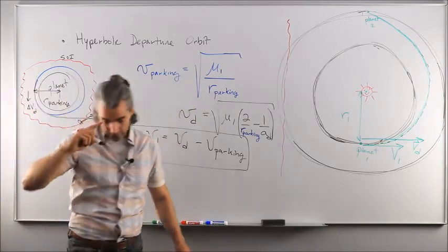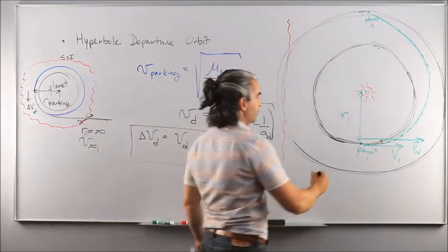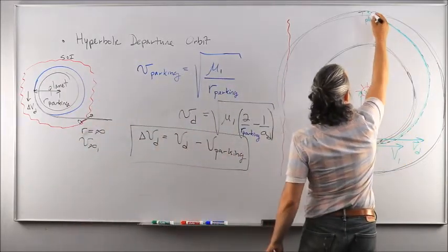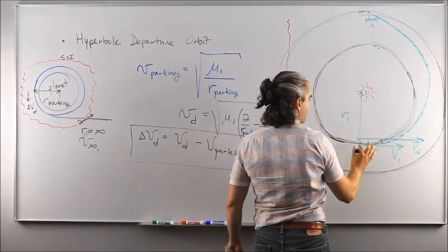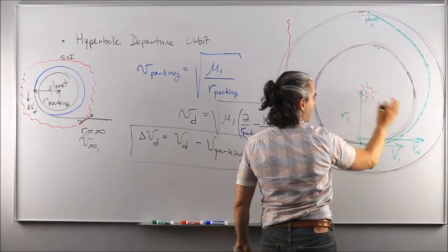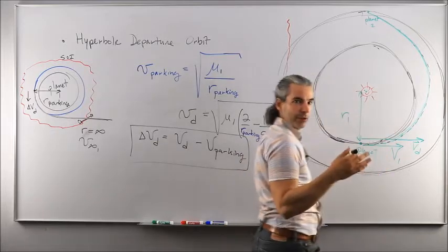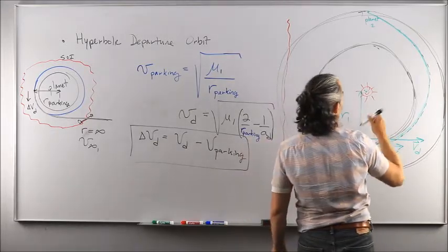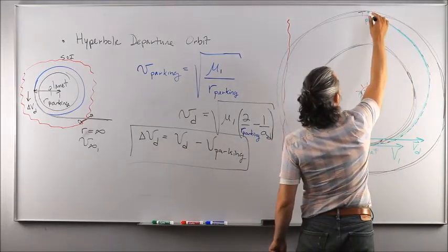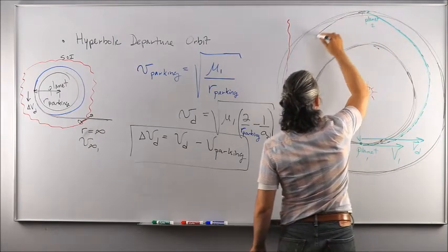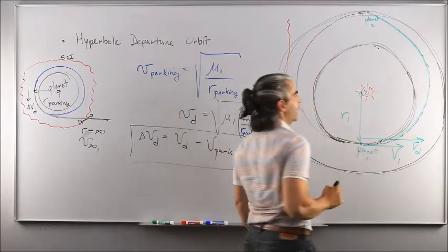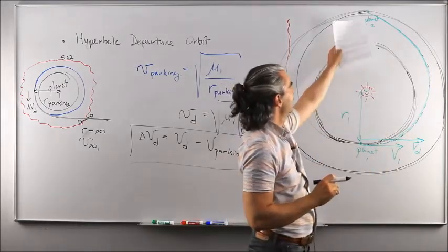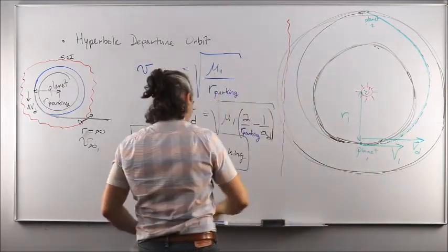Now, if you don't do anything, you will eventually reach planet 2 along its orbit, assuming that you timed the departure at the proper phasing angle, as we've discussed previously in this lecture. So you're going to reach planet 2 along its orbit, but then you're going to keep coasting along the transfer orbit forever. If you don't apply any other maneuvers here, that's what's going to happen.